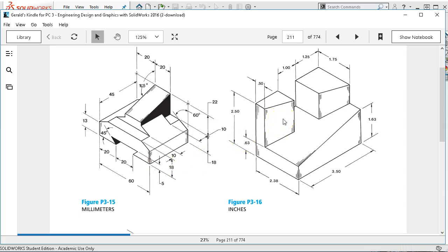So 316 is the one that really becomes counterintuitive. When we draw this shape, maybe the front angle, extrude it back, then this geometry really needs to be drawn on the bottom or on the top plane, so that when it extrudes through, it remains normal to the top. If we come back and sketch on this face, it's going to come off at that angle.